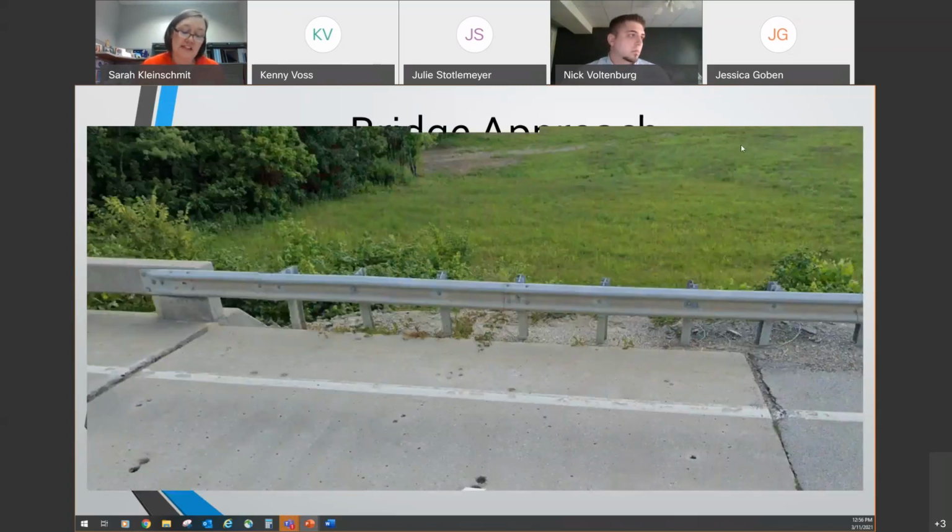This photograph is an example of a bridge end with no curb. I had a hard time finding an example photo with no curb on it. So if this guardrail were to be updated to MASH standards, you would use the top drawing of sheet 2 of Standard Plan 606-60 for the correct barrier transition. The minimum standard transition length, including the crash-worthy end terminal in this situation, is 87 feet 6 inches. Next.